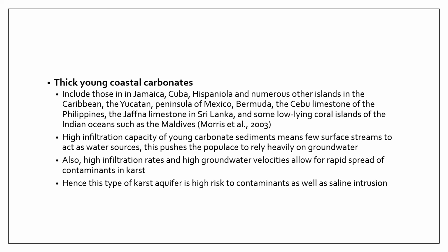As you will remember, these karsts have a high porosity, so they can have high infiltration rates, and in turn, high infiltration means you have a lot of groundwater recharge, but the consequence is that you don't have a lot of streams in that area. So the local populace will tend to rely heavily on groundwater for their water supply.